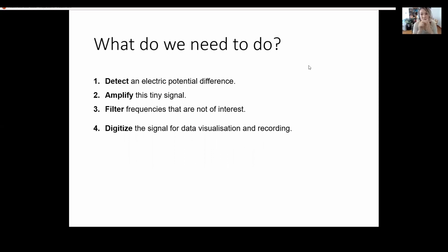An action potential, you have to be pretty close to the cell because it's one tiny action potential, and because it's so short, only like a millisecond, the chances of multiple action potentials overlapping and being able to sum and create a big signal is very, very small. So the first thing you're going to have to do is ask, all right, what frequencies am I interested in? And how do I make sure that my acquisition system protects those frequencies and gets rid of frequencies that I don't care about that could even interfere with my measurement?